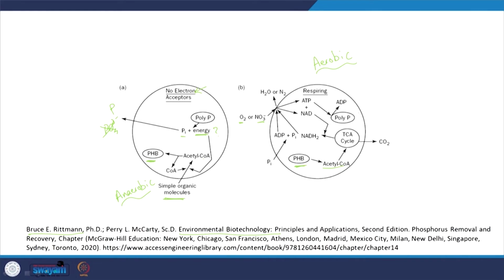And in this context, energy is released, and where does that energy, or part of that energy, go? It goes into formation of these polyphosphates. Again, obviously, for polyphosphate formation, you need phosphorus, and the phosphorus will be taken in from the solution. So, that is what happens. With this cycle, in the aerobic phase you will have the phosphorus being taken in. Again, more detail here, you can look at that. There is a role of acetyl CoA for which the energy is required, here at least. So, let us move on.